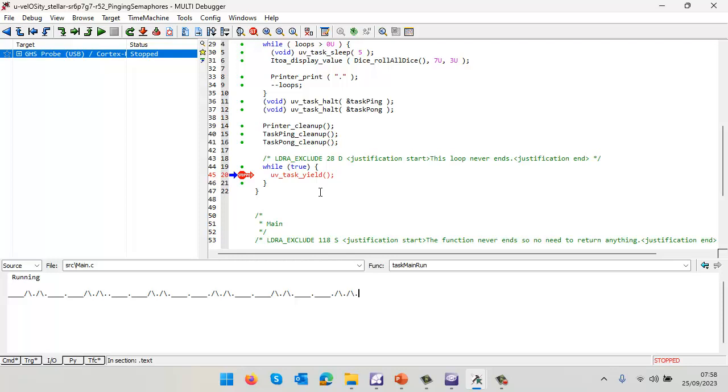I'd now like to see if it is compliant to ISO 26262 ASIL D. And that implies I need to first of all check that my code complies to a coding standard such as MISRA C 2023. I want to check the quality of the code, ensuring it's not overcomplex. I want to be able to execute the code and measure the structural coverage. I also want to unit test each individual function, specifying particular inputs and checking I'm getting the expected outputs. I'd also like to make sure that my code is not just safe, but also secure.